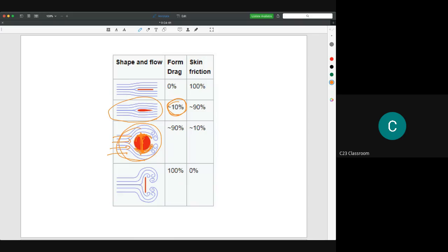And if the same plate is changed in orientation to become vertical like this, the total drag force comes from the surface, because the area here gives more resistance compared to the shear stress.